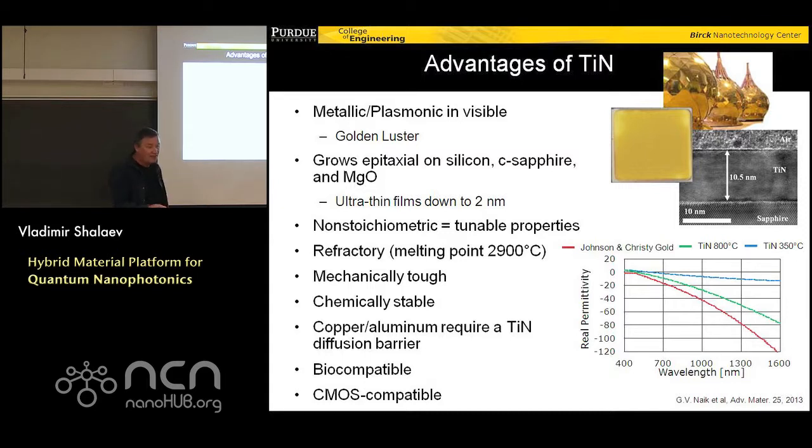And with nanostructures of gold or silver, even 400 Celsius is enough that your structure would be basically destroyed. There is diffusion, there is a creep phenomenon, and the shape changes, which basically means that you cannot use it in a durable fashion. So it's really important that the material can sustain elevated temperature, and titanium nitride is very stable at high temperatures. So it has lots of advantages, which clearly indicates titanium nitride is a great plasmonic material for a number of applications.